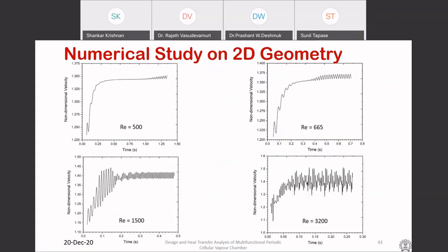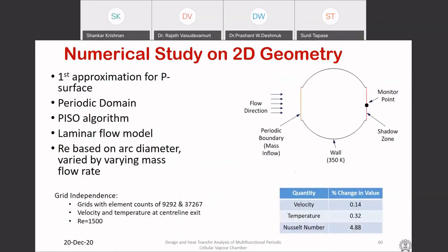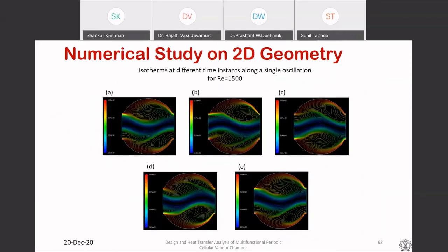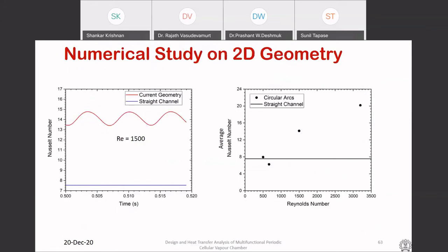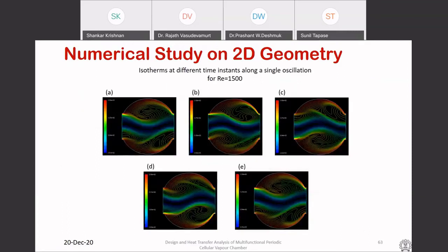In fact, Reynolds number meaning the speed, the velocity of the moving stream. There is a critical Reynolds number, and until you get to that point, you don't see any improvement. It is as good as any flat channel. But beyond a critical speed, it starts to show improvement and starts to actually have a sinusoidal type wave.